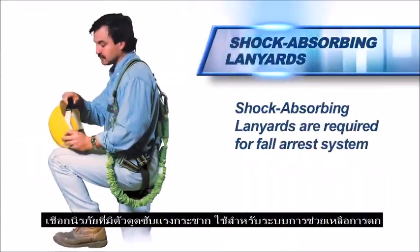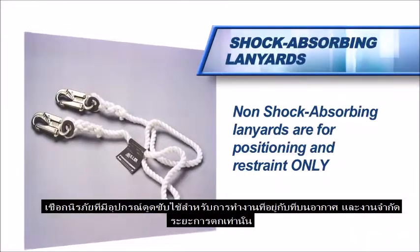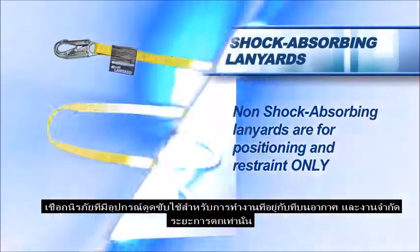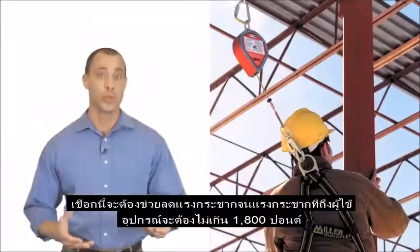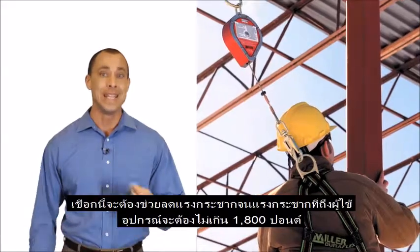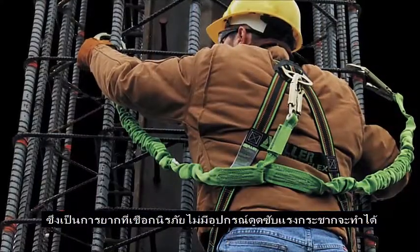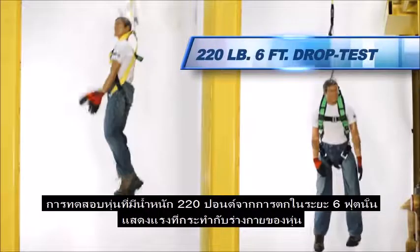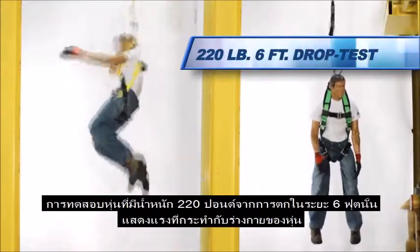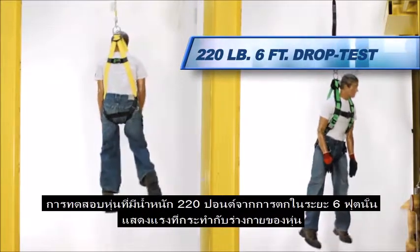Shock-absorbing lanyards are required for a fall arrest system. Non-shock absorbing lanyards are for positioning and restraint only. While both will arrest a fall, the maximum arresting forces when used together with a full body harness need to be less than 1,800 pounds. This is extremely difficult to achieve using a lanyard without a shock absorber. A test fall of a 220-pound mannequin dropping 6 feet with and without a shock absorbing lanyard demonstrates the forces on the body.